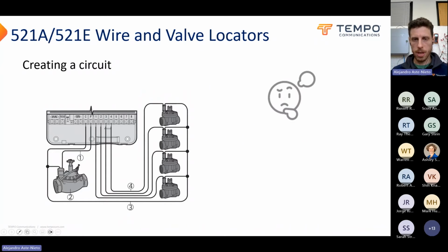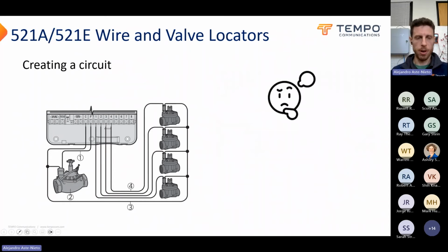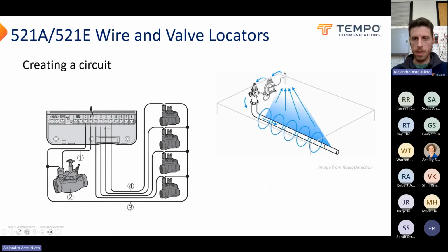So this is kind of thought-provoking, though, because there's no pre-existing grounding happening at the far end of any irrigation wires. They go out to a solenoid on the common wire. So how do we get grounding anywhere at the far end? Well, luckily the wire is bleeding off little bits of signal along the whole way, and it's sort of grounding capacitively. It's returning from the wire where it bleeds off back to the ground stake of the transmitter.